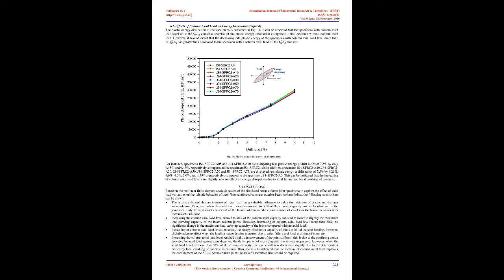It was observed that stiffness degradation of specimens had a critical influence only in the initial loading cycles, and the stiffness values after a 2.5% drift ratio of loading were approximately the same in specimens with different axial load ratios, but specimens under very high axial load showed slightly greater stiffness degradation than specimens with low axial load. Fig. 15. Stiffness degradation of specimens.